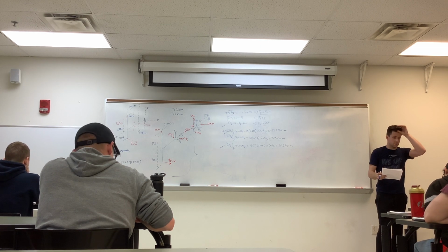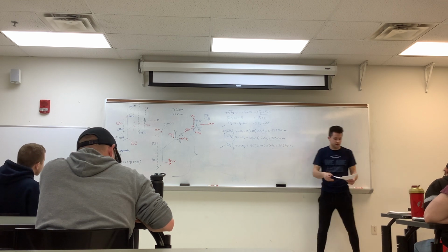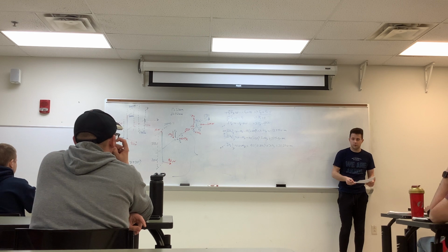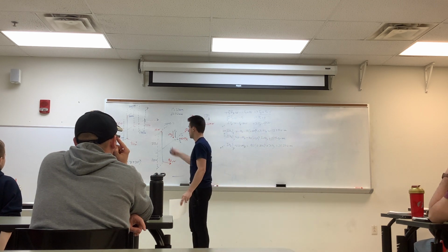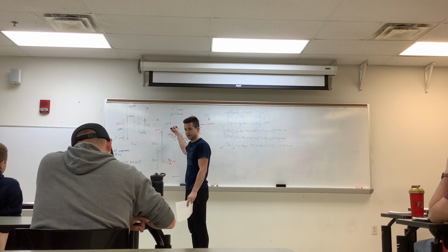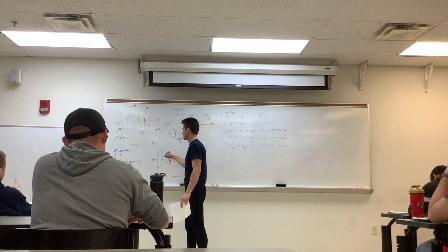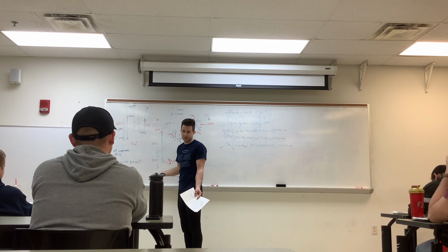Are all the measurements, those are in millimeters on the graph, right? Yeah, I'm just converting it to meters here. Okay. How does that 55 affect the moment in y? So it is a force in the z direction. When you're calculating your moments, any force in that same direction is nullified because it doesn't cause any kind of moment about it.